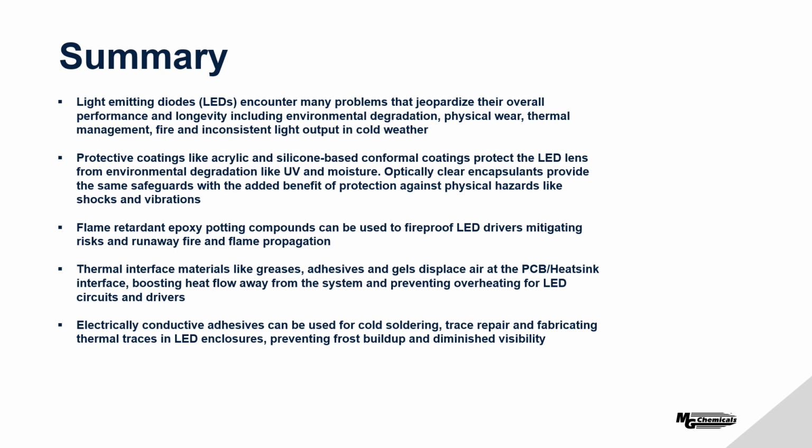Flame retardant epoxy potting compounds can be used to fireproof LED drivers, mitigating risks of runaway fire and flame propagation. And for that, we have our 834 series of flame retardant epoxy compounds. Thermal interface materials like greases, adhesives, and gels displace air at the PCB heatsink interface, boosting heat flow away from the system and preventing overheating for LED circuits and drivers. And for that, we have three different types of compounds: thermal interface adhesives, greases, and gels.